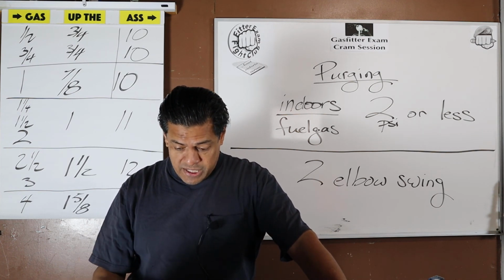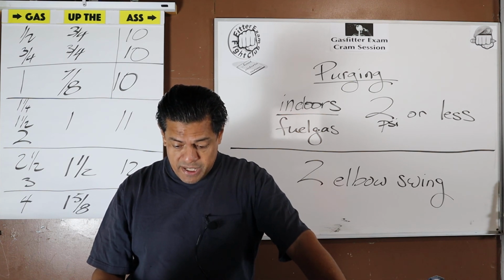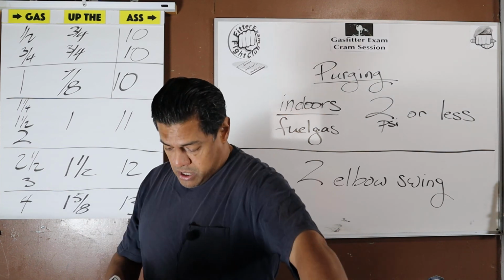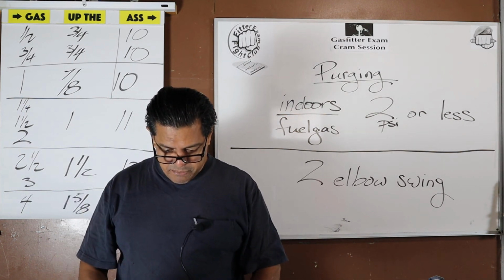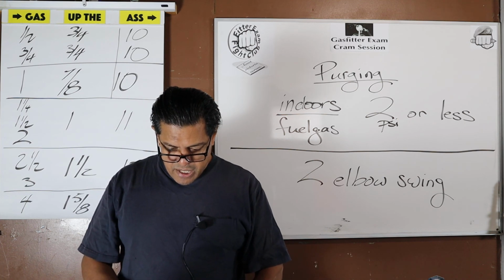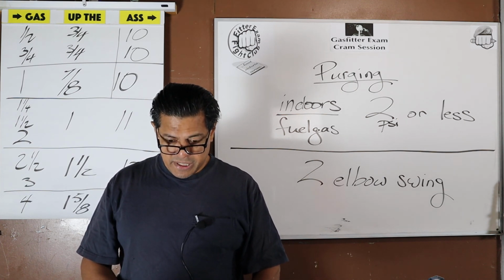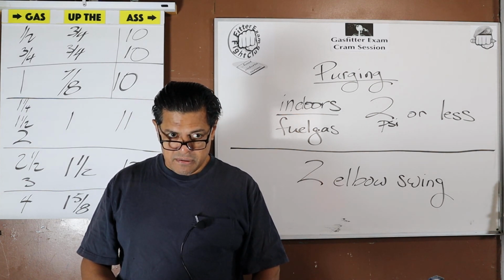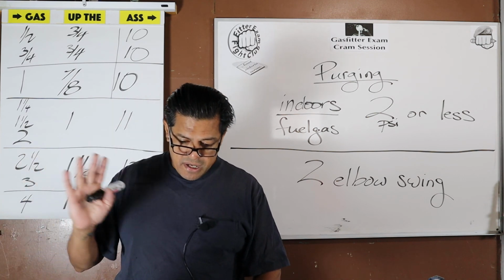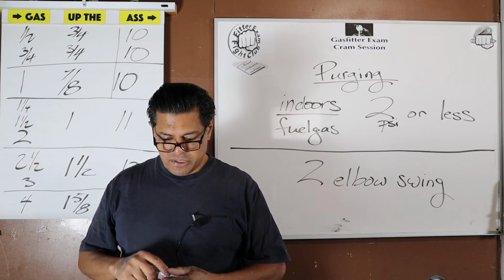Question 14. Gas piping entering through a foundation wall underground shall be protected by encasing it in a protective sleeve. So we're generally talking about the service. Okay, there could be other situations, but more often than not, it's the service.